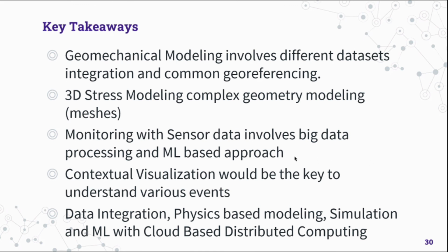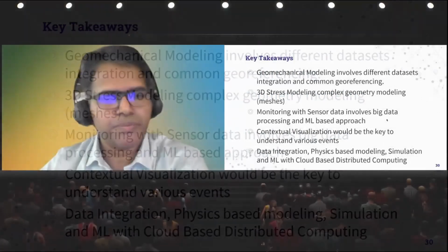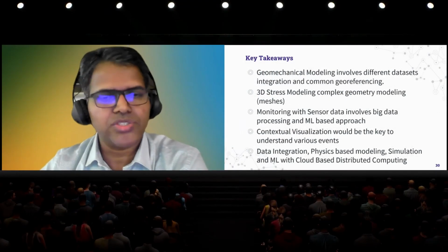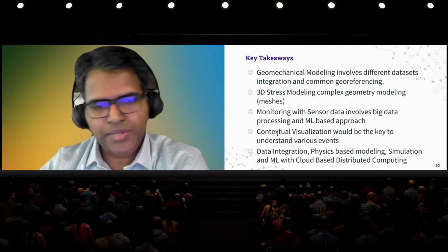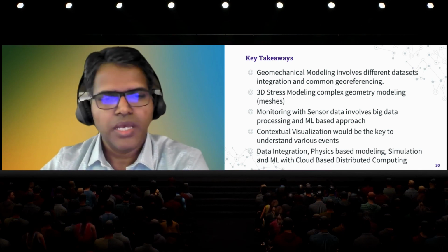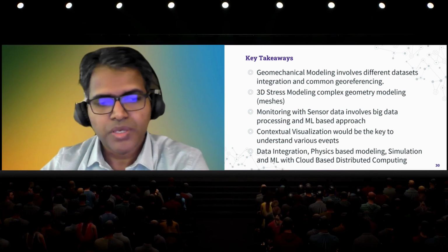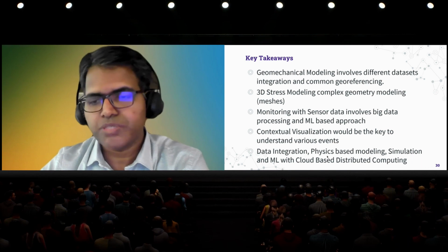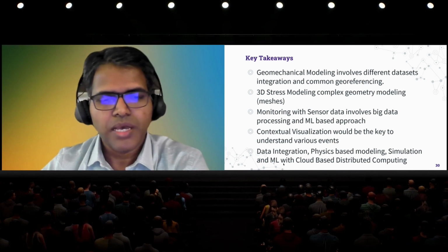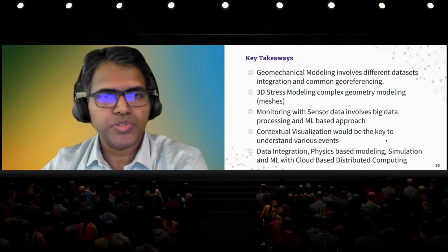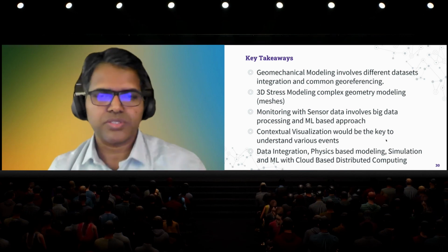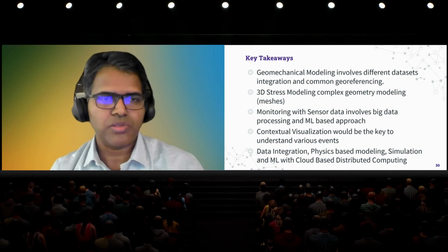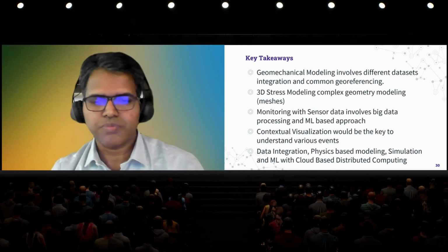And then monitoring with sensor data involves big data processing and also machine learning to extract rich data. And in all of these, ultimately, you have to come up with a contextual analysis to understand various events. And as I mentioned, the data integration and also physics-based modeling and simulation modeling with ML, along with cloud-based distributed computing, is making this whole process of modeling complex geology and also the stress fields with geomechanics possible.